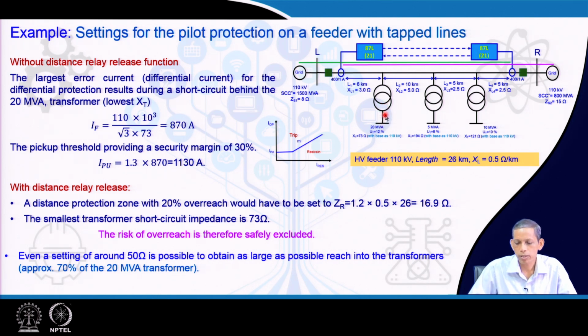So, the largest capacity transformer will have a smaller impedance relative to the other transformers, and if we create a 3-phase fault beyond the transformer, the corresponding fault current will be more significant beyond the transformers in the tap lines. Therefore, we consider the highest transformer capacity, so that the fault just beyond the transformer gives IF equals voltage level.